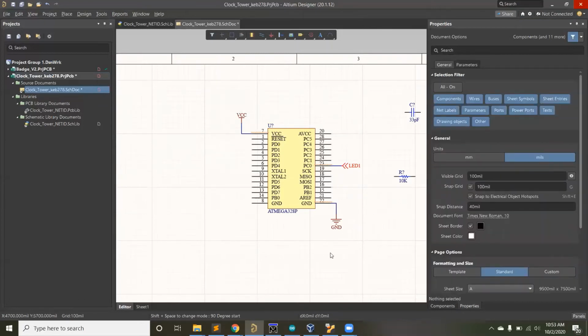So make sure you read the data sheet for this. There's some pins that you should not use as input-output pins. For instance, if you use TX RX for this, it'll be very difficult to program it because typically I program these by just putting them onto an Arduino Uno and then program it from there. And TX RX is used to connect that Arduino Uno to a computer,